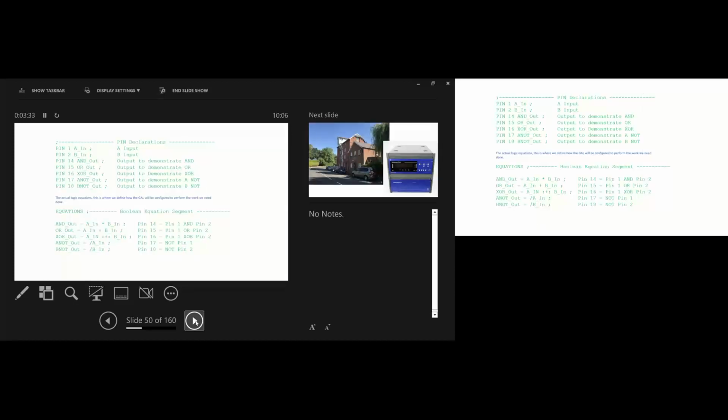You had to be a little bit careful with the 22V10 because it was a one-time programmable device, so it was in the bin if you made a mistake. To program it, we used a language called PALASM, for those who are old like me and may remember that. It was the first time that we started using text to describe the design rather than schematic designs.